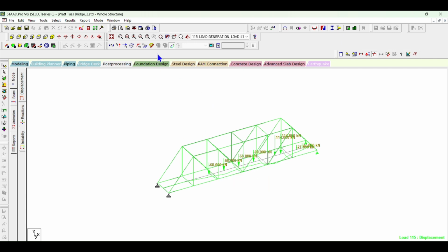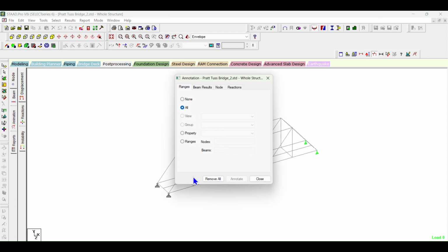So we can see here that our bridge is analyzed. Now we want to see the result. This is a truss. So in a truss, the members carry only axial force, either tension or compression, and we need to find the force in the members. Since we have run the load at the center, and the structure is symmetrical, the values in both the trusses will be the same. So go to results, view value, reactions, global Y, and anode. So we have started the global Y reactions.